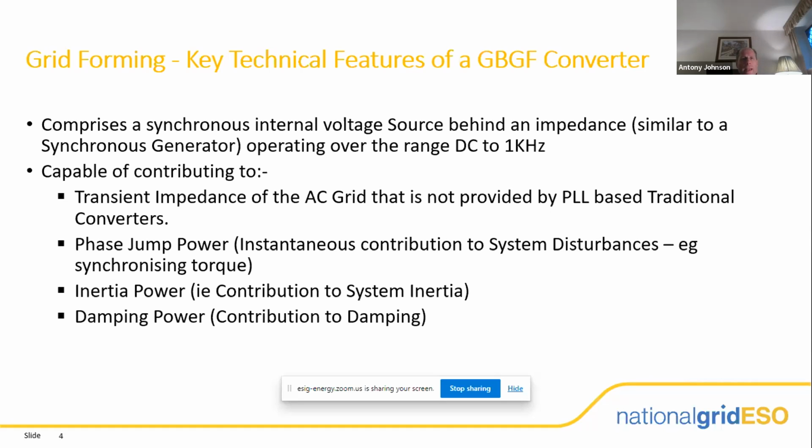We also need inertia power, which is the contribution as the speed of the system starts to change. You'll also get the injection of power. So we know that the rate of change of frequency is equal to 1/2H times the power difference. So we get a power inertia or a power injection from a frequency change, which is another element that we want to achieve. And also, in addition, we will get a small contribution from damping power.